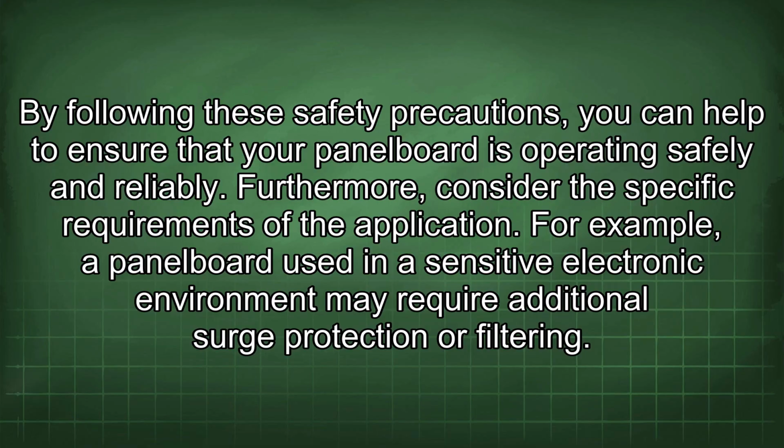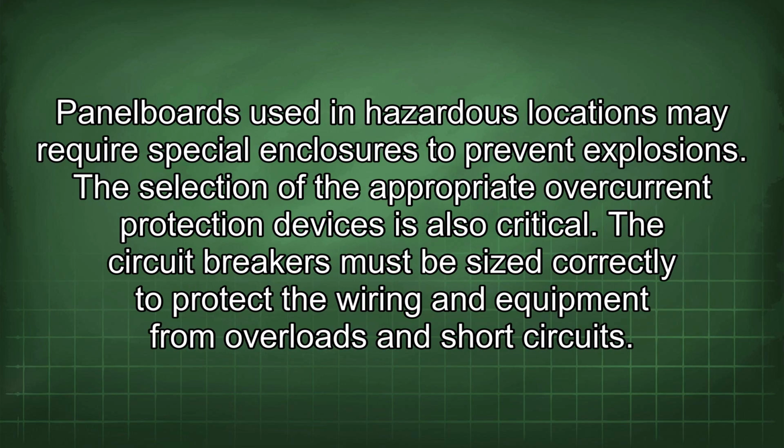For example, a panel board used in a sensitive electronic environment may require additional surge protection or filtering. Panel boards used in hazardous locations may require special enclosures to prevent explosions. The selection of the appropriate overcurrent protection devices is also critical.